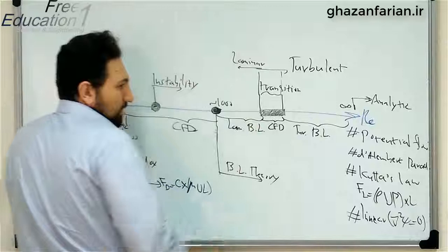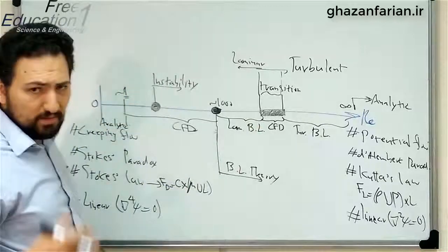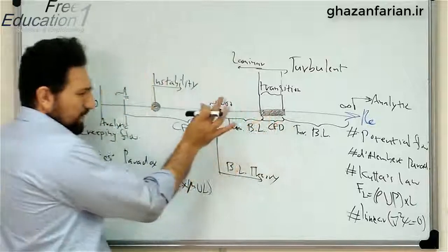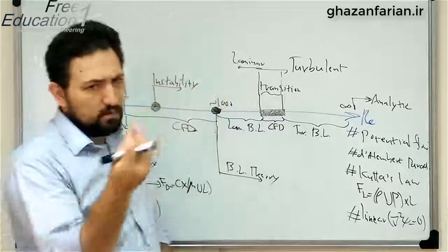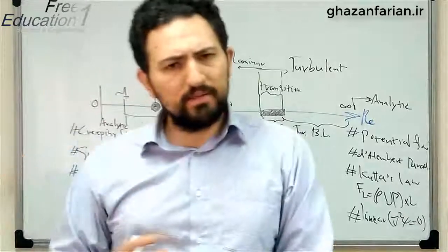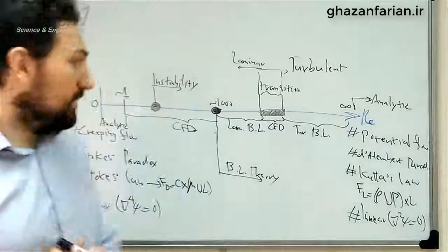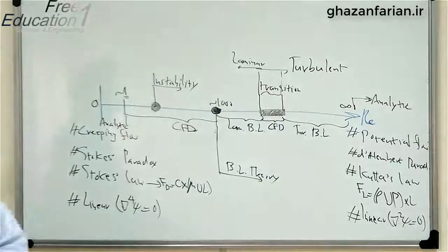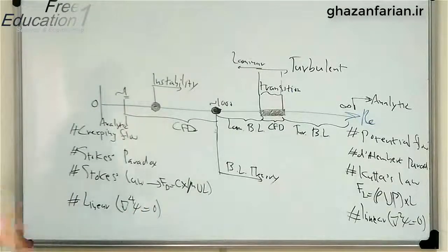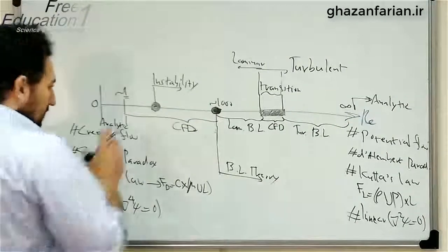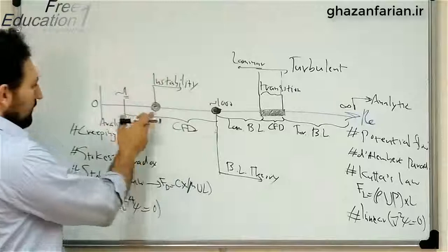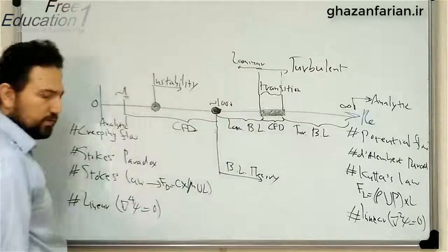So we can record many videos about the behavior of the flow in this transitional regime. But for example, for a flow in a circular pipe, this transitional Reynolds number is about 2000. And this critical transitional Reynolds number differs from one system to another based on the geometries or the surface roughness. But what's important in this video is that we have three critical Reynolds numbers here.